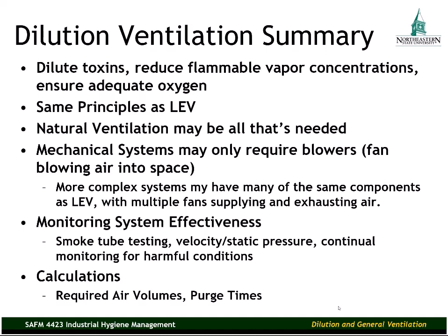We talked about monitoring the system's effectiveness. We smoke tube testing, look at the velocity, the static pressure. But more importantly, I think, than anything, is once we get our system set up, we need to continue to monitor for harmful conditions in that space.